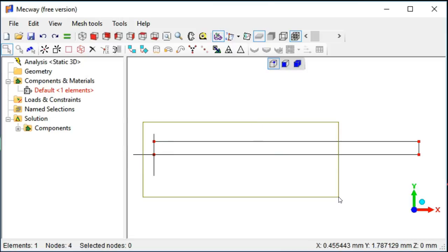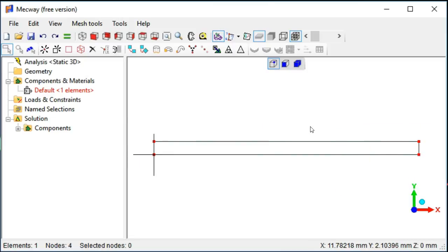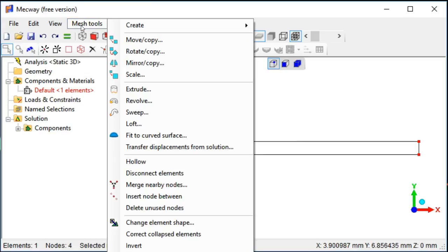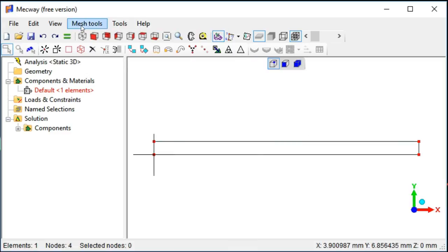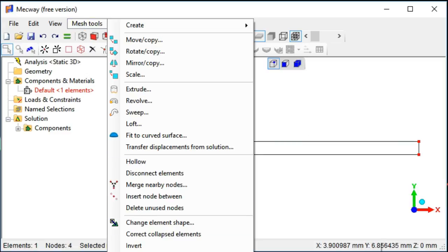Now I want to divide it up into smaller elements. The way FEA analysis works is that it basically takes the structure that you drew and chops it up into many different small parts, which it then combines using Newton's equations or other dynamic equations. And by connecting these individual elements, hence the term finite element analysis, you're able to come up with a final solution for complicated structures. In this case, we're just going to verify our analytical solution to see how realistic it is.